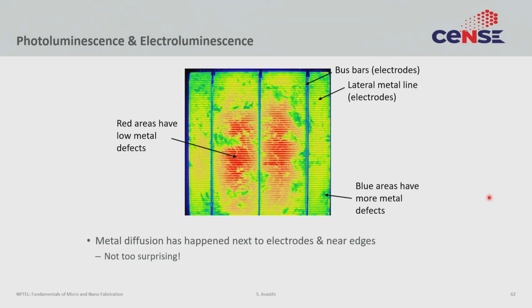So, you can see that when you process a wafer, it does not come out uniform because defects can be randomly placed. That randomness and distribution of the defects is also visible in the EL image. So, you can tell that the middle of the wafer, which was probably not touched by anything, is cleaner, the edge of the wafer is more dirty, and so on. Sometimes, if there is a certain systemic problem, you can look at an image and see where the systemic problem is coming from.